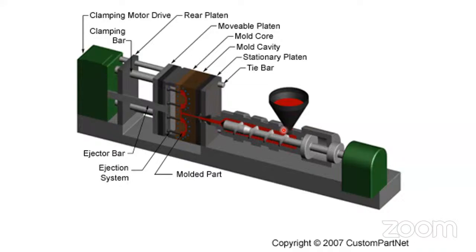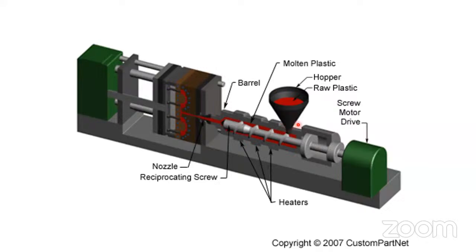I will show you this slide. See now here. This is the throat of the hopper. At this throat of the hopper, a cooling system is provided. The cooling system is a spring-type structure that surrounds this throat, and it has an inlet and outlet. From the inlet you pass chilled water, and at the outlet the hot water comes out.